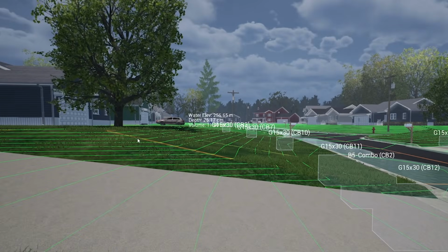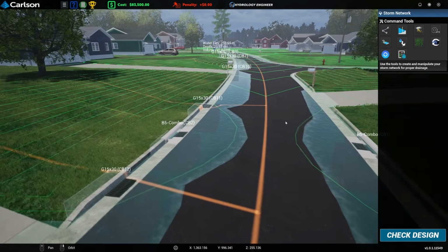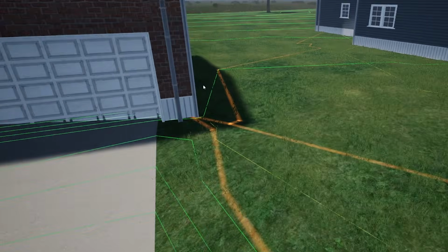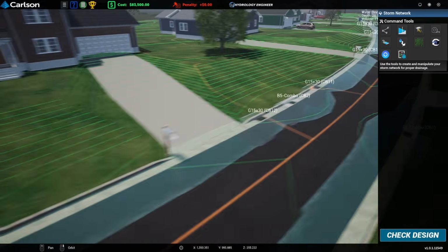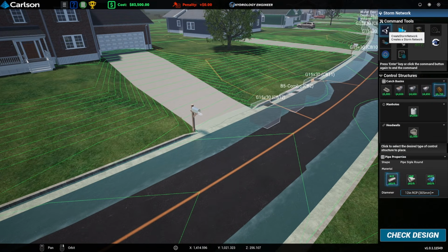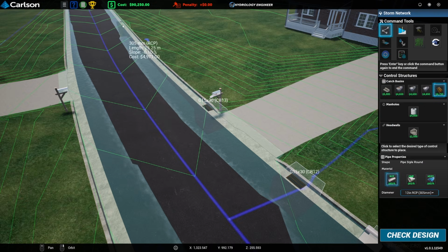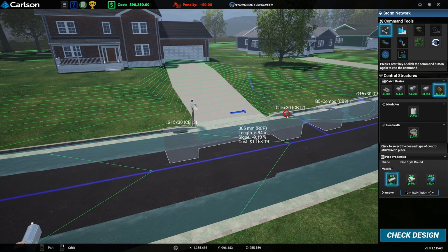behind. Can you see this sloped bank? Most of the water that lands on this grass will be flying towards our road. We've also got this quite long driveway. We know that we've now got all these downpipes, so we've probably got all of that roof contributing. So what it may be worth doing is just shoving another gully up there to take most of this water, because basically all of that area is contributing towards this gully.